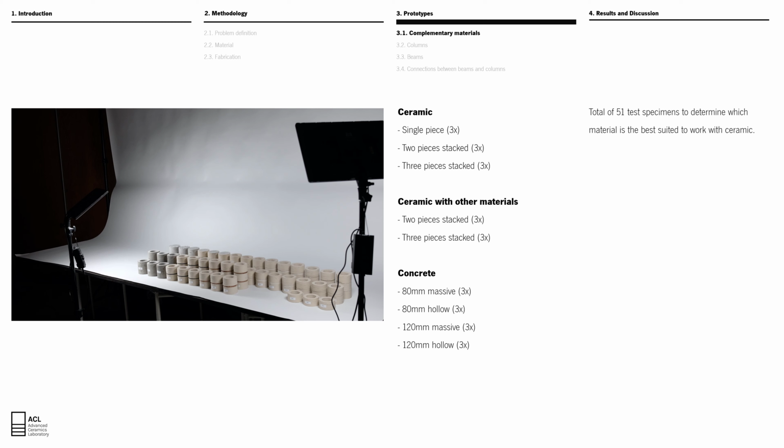Each of these materials was submitted to compression tests to evaluate which one is best suited to work with ceramic. For the tests, we made 3 specimens for each material, with 2 and 3 stacked ceramic pieces, and we compare with specimens without separation material and with similar sized concrete specimens.